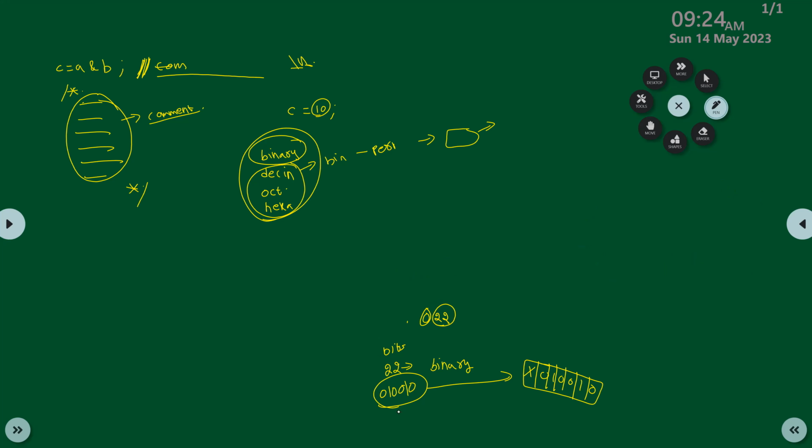So these are the different ways to define variables. If you define 2'b and give 110, it will throw a syntax error. It won't discard anything. That error might depend on the specific version of the tool, but this is not the correct way to define a variable. Few tools will discard, but that depends on the tool versions you are using. Ideally this is not the correct way to define a two-bit variable.